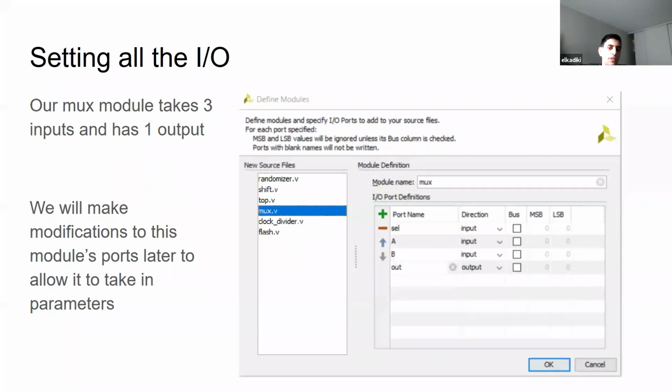So the mux, we got the select, the A, the B, and oh man, we got a C now too. Forgot to change that as well. So yeah, A, B, and C, and the select should also be another bit wider, right? Yeah. The main reason why we had to expand this was due to the addition of the pseudo-random number generator, so you can display all of them at once on the board. The unfortunate side effect is now we have the 4th state, which is blank.